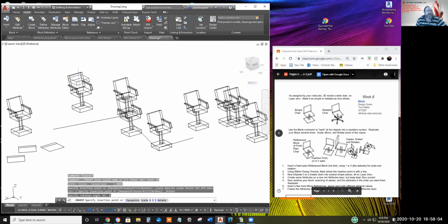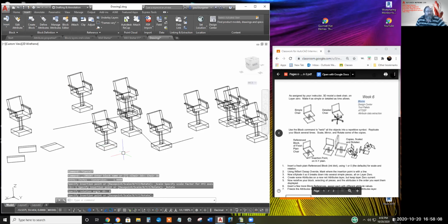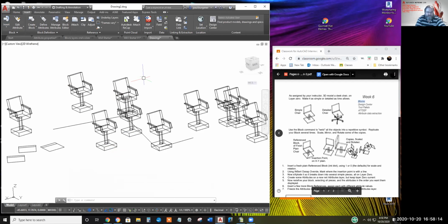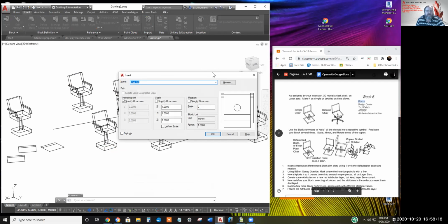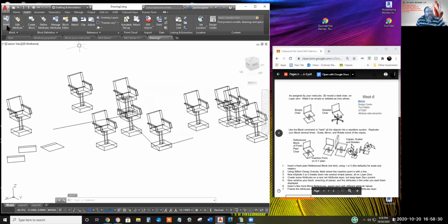We can click on a 3D chair and plop him somewhere in the world UCS system. I prefer if you type the word insert or simply I enter, it's hard to show, but they come out alphabetical, and I think they're easier to find than on this icon list on the insert box here.